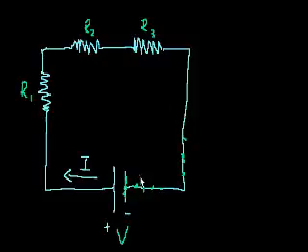So before you encounter an element in the circuit, before you encounter a device, you could view this ideal conducting wire, just from a schematic point of view, as an extension of the negative terminal. And similarly, you can view this part of the wire right here as an extension of the positive terminal. And the reason I want to say that is that it doesn't matter where you measure the voltage.